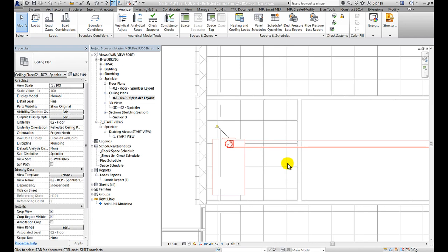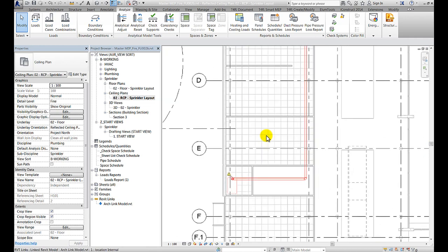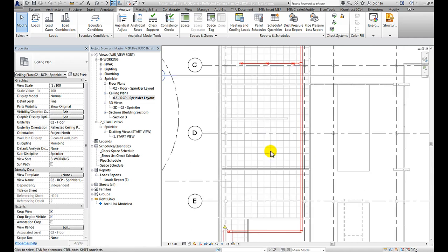This tool can be useful by allowing you to quickly scan through your model and identify the problem areas that need attention. This can be helpful when you are sizing pipe especially, as if you have disconnects in your pipe system, your pipes are not going to size and remain connected properly.